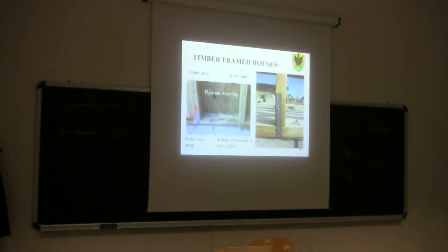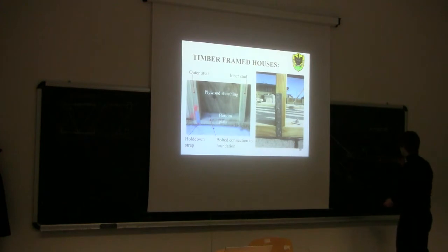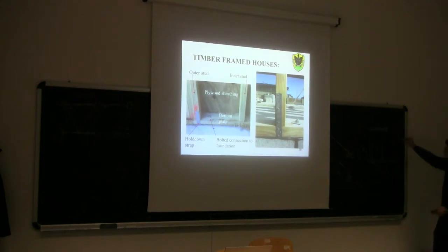Okay, so other photos. So outer stud, bottom plate, inner stud. Note that the inner stud and the outer stud are supported by the bottom plate. So there is a detail done in this way. Bottom plate, inner stud, outer stud, inner stud, and outer stud. Meaning that if there would be some compression here, this compression will stress the bottom plate perpendicular to the grain. So we see immediately a problem here of compression perpendicular to the grain. Okay?